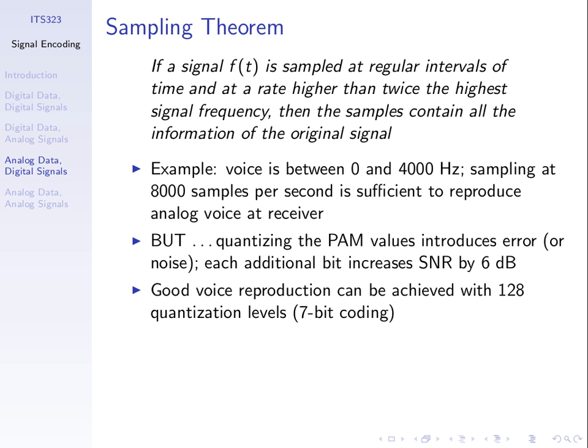Considering the highest frequency component of that input, let's call it simply f here. If f is the highest frequency component, if we sample at a rate greater than or equal to 2 times that, f, then that's sufficient for the sampling rate. When we do that sampling, we'll be able to reconstruct the original analog input, recovering all the information from the analog input from that data. So if we know the structure of the analog input, and in particular we know the highest frequency component, say f, and we sample at 2f, then we'll be able to reconstruct that analog input.